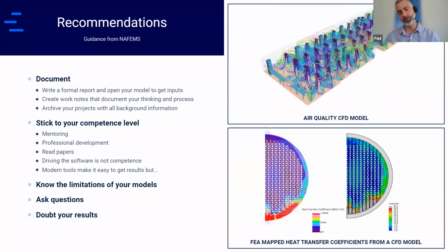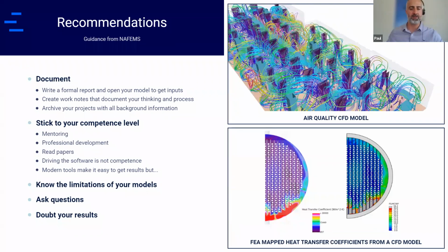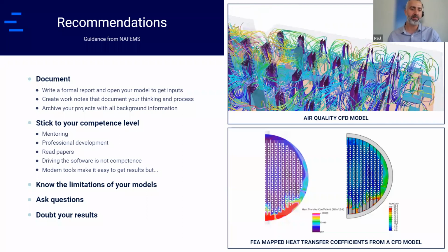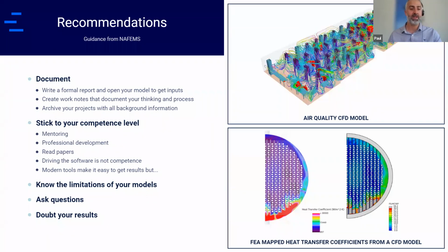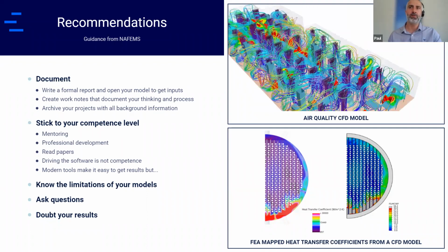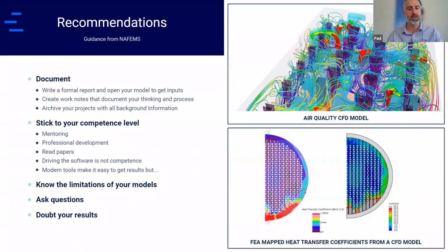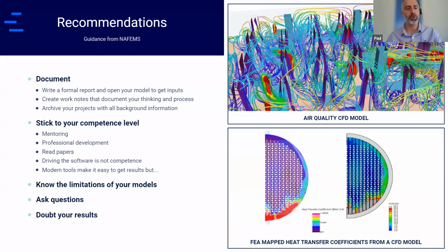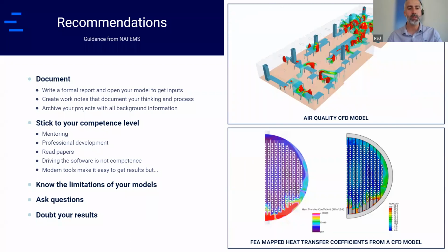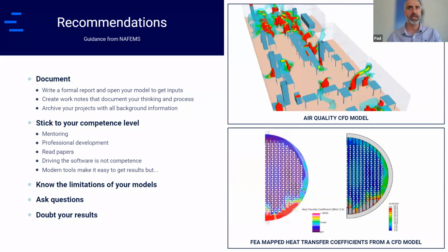And when you come to get your inputs for your model, I still do this: you could use an Excel spreadsheet that you use to derive your inputs, or you can open up the model, go and click on the field where you input the value and get it from there. That gives you an added level of confidence that you've documented what you've modeled, not what you thought you've modeled. And sometimes when you're writing a report, you can find things that you hadn't picked up on during the usual Q&A process.